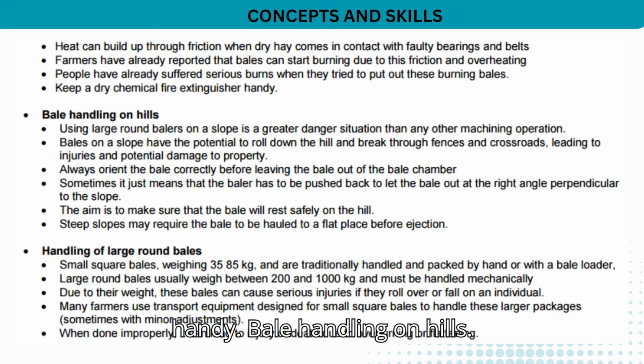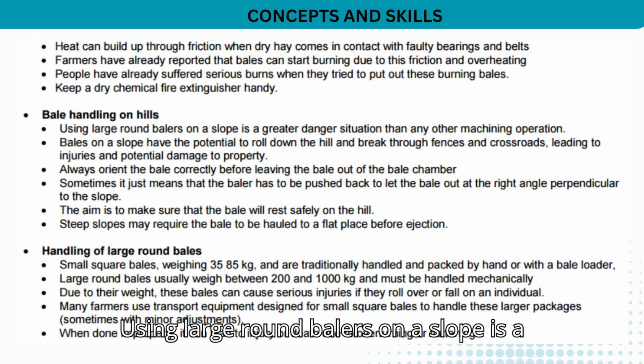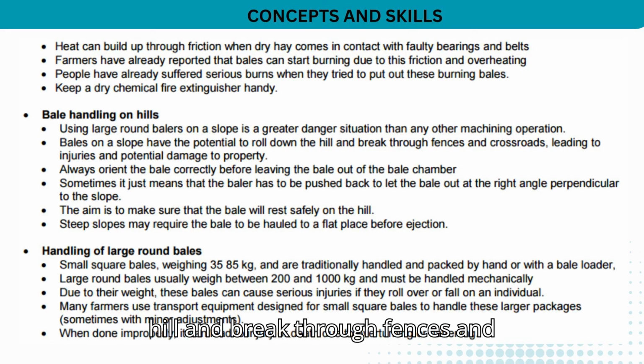Bale handling on hills. Using large round balers on a slope is a greater danger situation than any other machinery operation. Bales on a slope have the potential to roll down the hill and break through fences and crossroads, leading to injuries and potential damage to property. Always orient the bale correctly before leaving the bale out of the bale chamber.